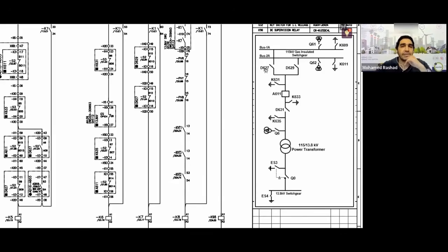Let's see together. We said now that the disconnector switch is something that opens and closes without load, because if it opens and closes on a load, it means that electrical current will pass through it. That's why we even said it is used for you to choose if you want to connect your circuit breaker to it only. Whether the power is imported or exported, meaning whether you're taking power from the bus bar and giving it to the line, or the power is coming from the line and you are giving it to the bus bar.